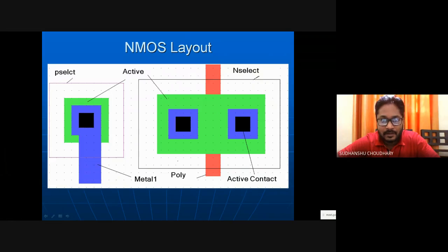First thing, you need to understand that this white background, which has grids, these small dots, is always a p-type background. In fact, the wafers being produced today are also p-type, and this can be ensured by putting a p-type impurity in the Czochralski process. We had the molten silicon in the crucible, and in that molten silicon you put some p-type impurity, so that the cylinder or ingot which is created is completely p-type. So p-type wafers can be produced that way.